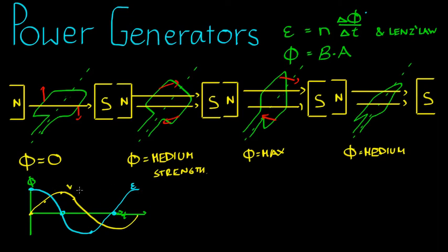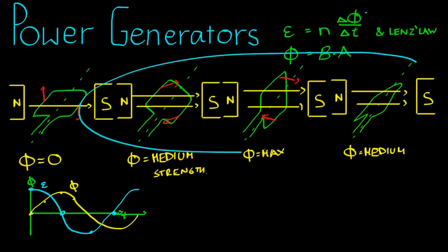This indicates to us, since the voltage is positive here and negative here, it's hinting, oh no, I've got those the wrong way around. This would be the EMF. Oops, no. Sorry, this is the flux, and this is the EMF. Since the EMF is positive here and negative here, it's telling us the voltage must reverse direction. Yet let's use Lenz's law to determine the direction of voltage, the direction of current, and whether the voltage is positive or negative at all these different points here.